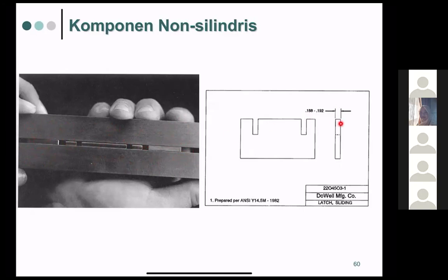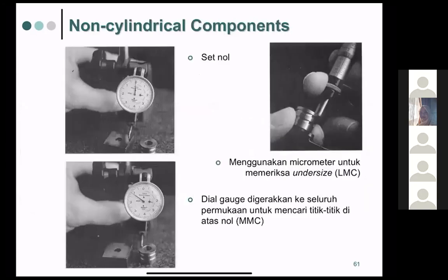And for non-cylindrical components here, we use a micrometer to check the LMC, and a dial gauge like this to check the MMC.